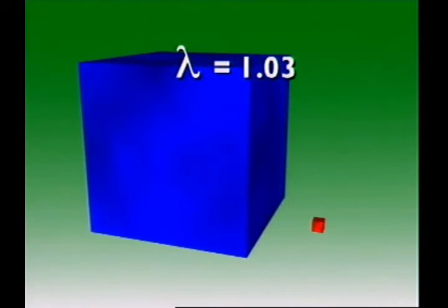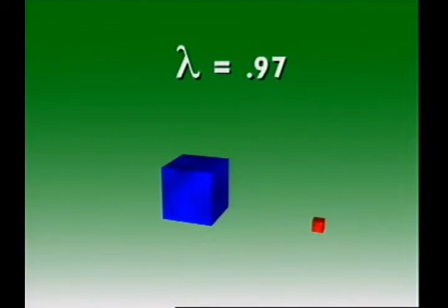If an air-fuel mixture has a higher figure, say 1.03, there is more air in proportion to the fuel than 14.7 to 1, and the mixture is slightly lean. A mixture with a lower lambda value has less air, proportionately, than fuel, and the mixture is slightly rich.